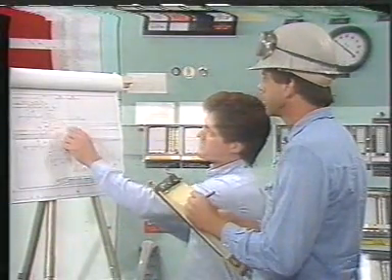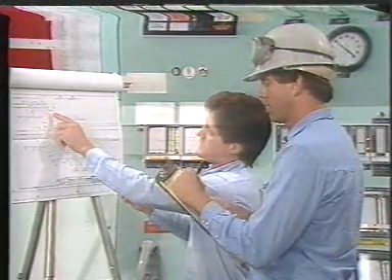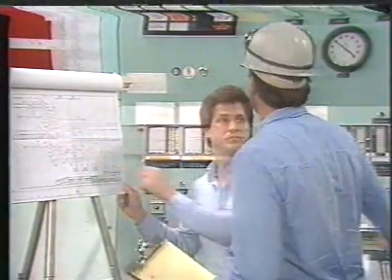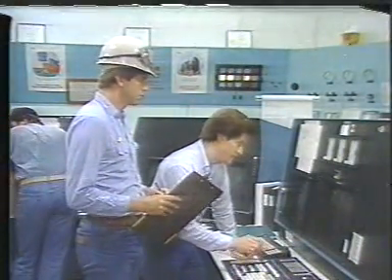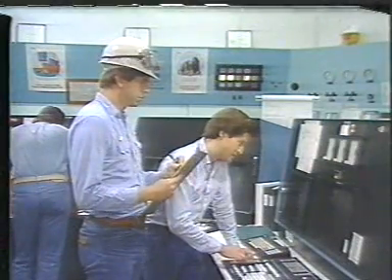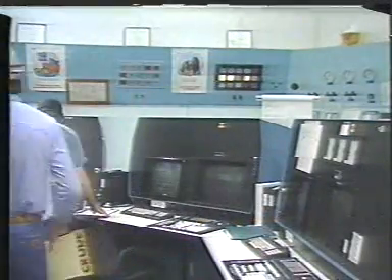One way to remove heavy material from the top product is to increase the reflux rate. Another way is to decrease the reboiler temperature. In this example, you would probably decrease the reboiler temperature because of the energy savings. However, increasing the reflux rate may be the quickest way to remove heavy material from the overhead product. Let's review the control procedures that are used during the normal operation of a distillation column and work through some more problems. Stop the tape and turn to section 2 of your workbook.